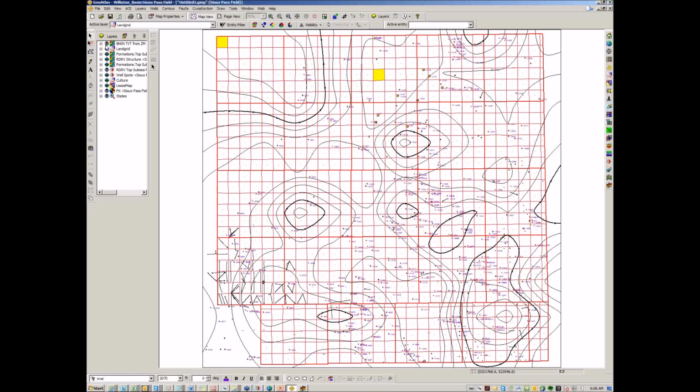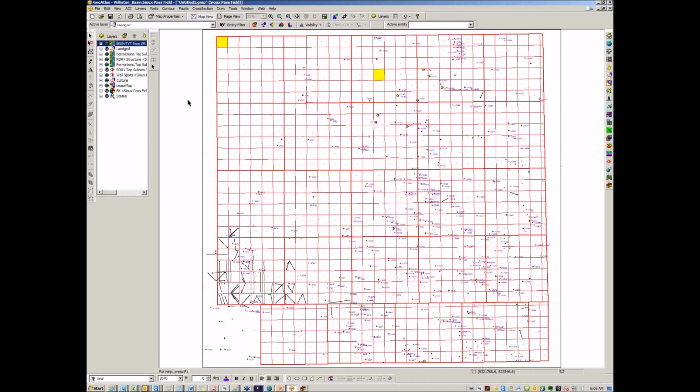Okay, in addition to using Zone Manager, other common sources for data within Discovery, within the modules, I can feed data in from SeisVision or SMART Section. But in this case, I want to go to an external data source. I've got a top pick that's not really in my database, and that's the Mission Canyon. I don't so much have it picked on my sections, but I do have an XYZ data file from an